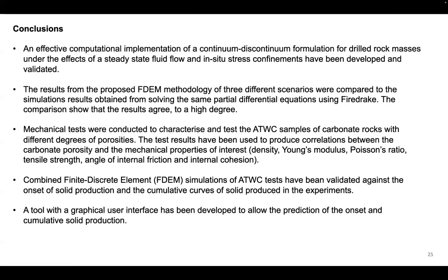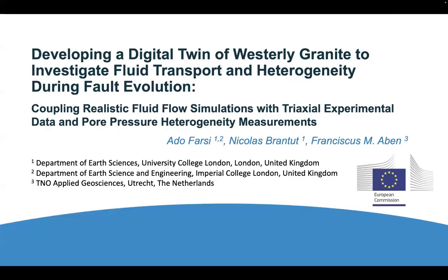Combined finite-discrete element simulations of advanced thick wall cylinder tests have been validated against onset of solid production and the cumulative curves of solid produced in the experiment. As I showed you, we have a very good match. And we developed this graphical user interface that has been used by engineers in PETRONAS. So it was a pretty successful research that we conducted.